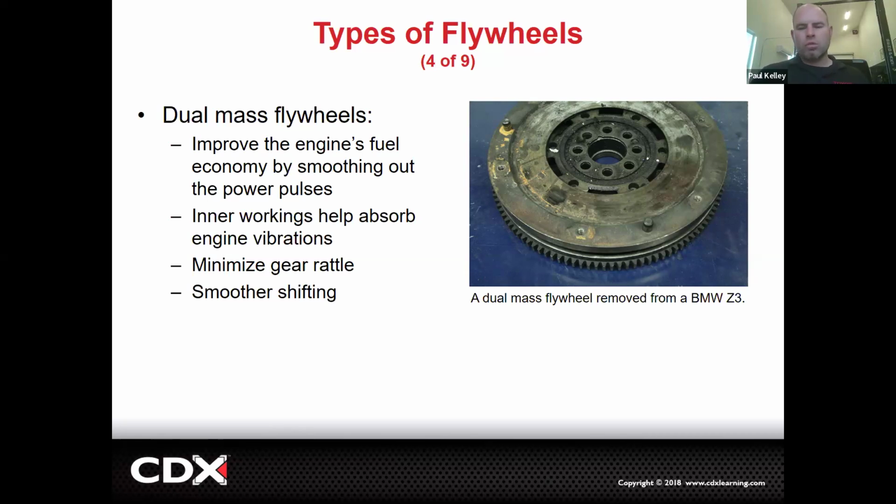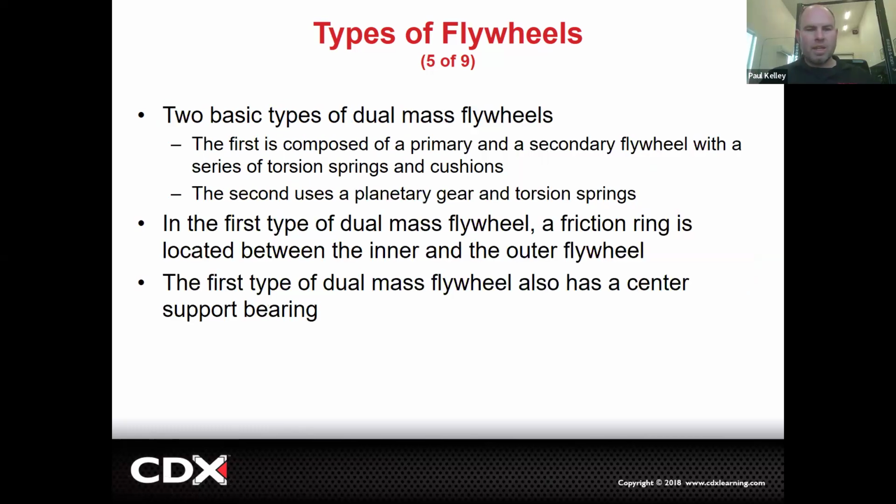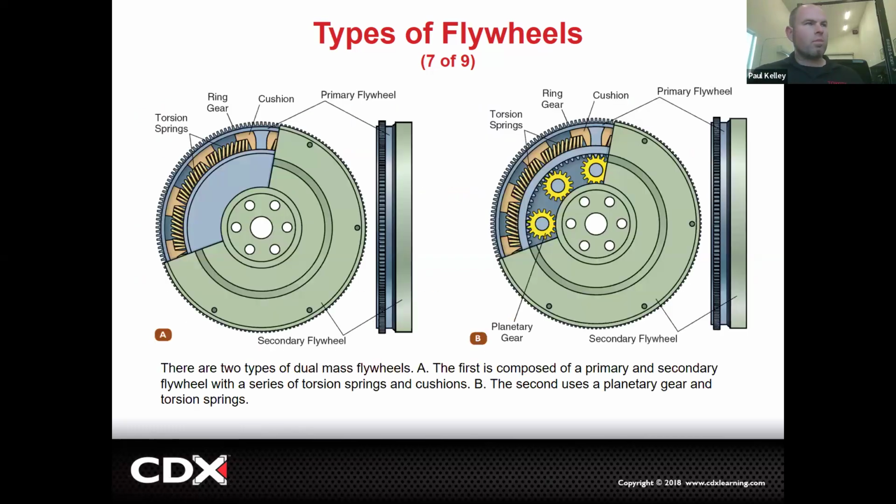Other thing here is it's a dual mass, so you actually can't really cut it anyway because they move a little bit independently. So I wanna have you remember what this looks like. See how it's bigger, it's thicker, it looks a lot more complex. It is. So in the center we have kind of like a blue disc, and that bolts directly to the flywheel. And then we have springs, dampers, sometimes little rubber bumpers, all sorts of little funky mechanisms.